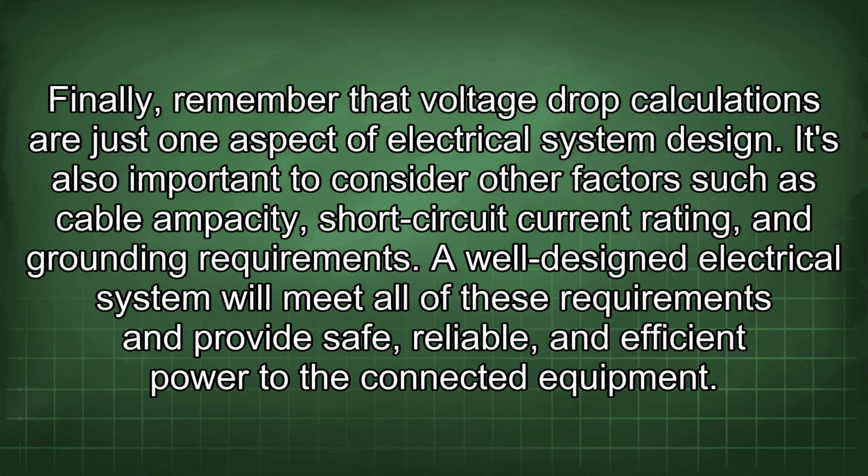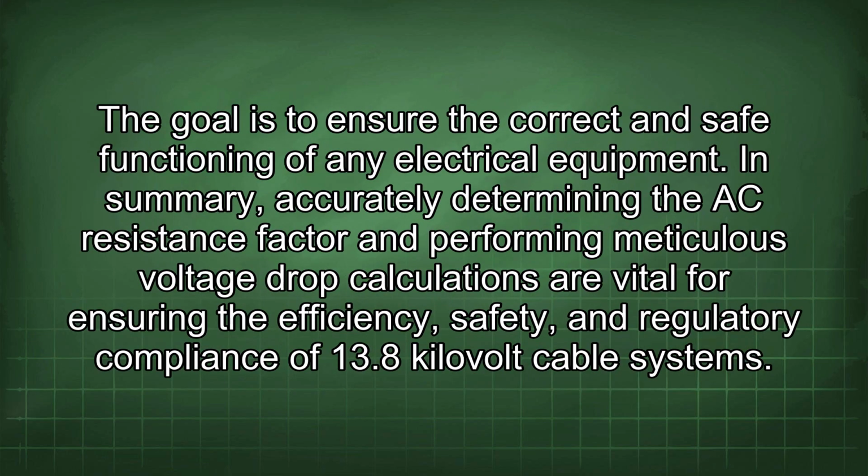Finally, remember that voltage drop calculations are just one aspect of electrical system design. It's also important to consider other factors such as cable ampacity, short-circuit current rating, and grounding requirements. A well-designed electrical system will meet all of these requirements and provide safe, reliable, and efficient power to the connected equipment. The goal is to ensure the correct and safe functioning of any electrical equipment.